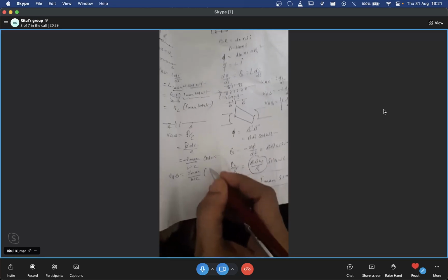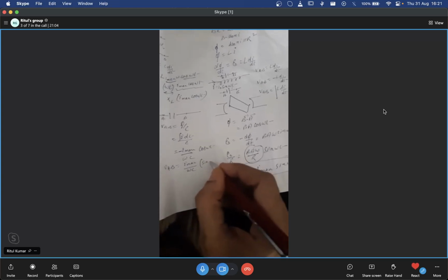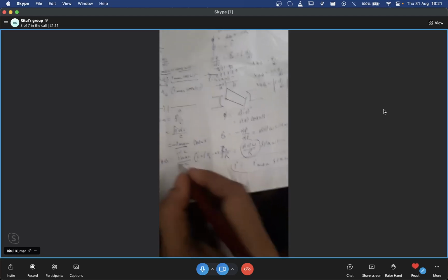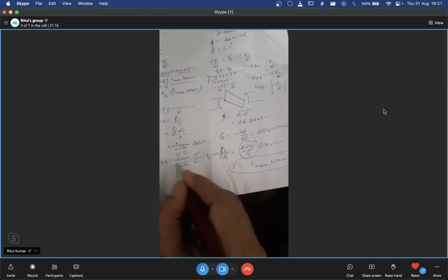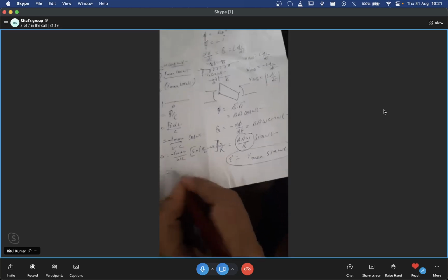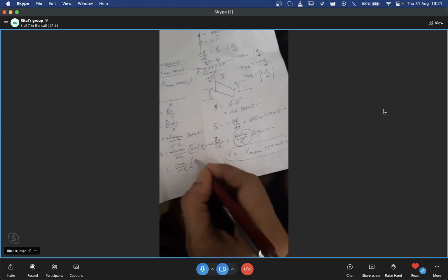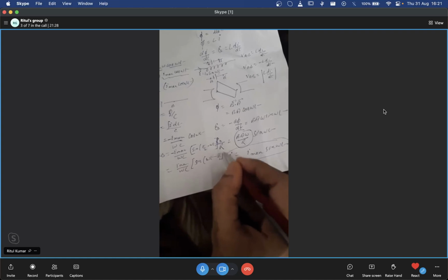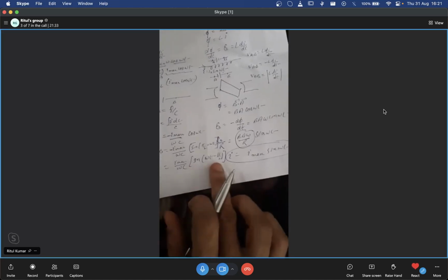So two ways of using it. Sine of the angle 90 minus omega t I use. So I'm using both, by the way, for you. Okay, done. And the minus sign is out. Sine 90 minus omega t is cos omega t, correct? Now I max by omega C, I take my negative sign inside. What I am getting then is sine of omega t minus pi by 2. Do check and endorse it. Is it fine? Yes. Okay.